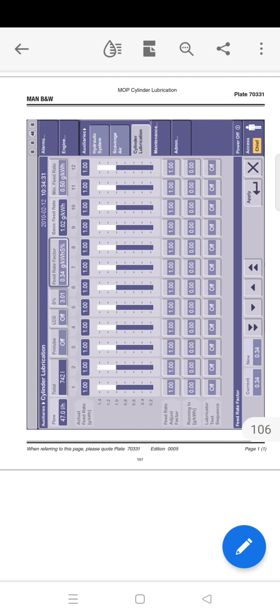The actual feed rate is shown as a bar graph for each cylinder. Each individual cylinder shows the actual feed rate per cylinder after the influence of the limiters, load control, etc. If the feed rate due to the low load exceeds the maximum display capacity, that is 1.45 gram per kilowatt hour, the full bar is barred and the upper display on the bar graph shows low load.